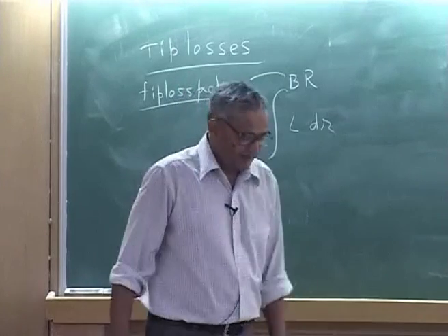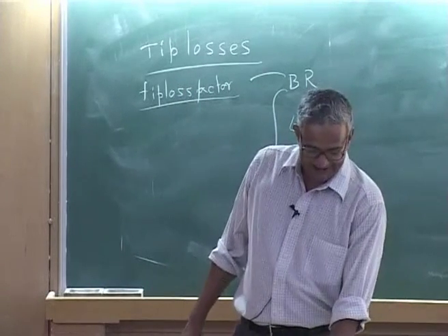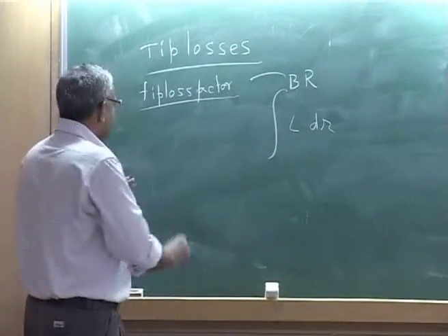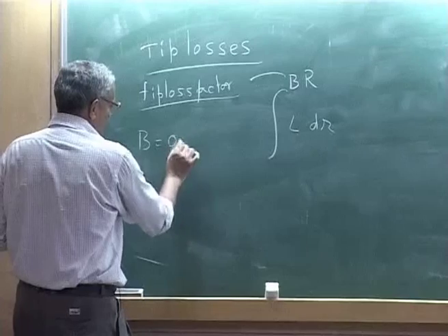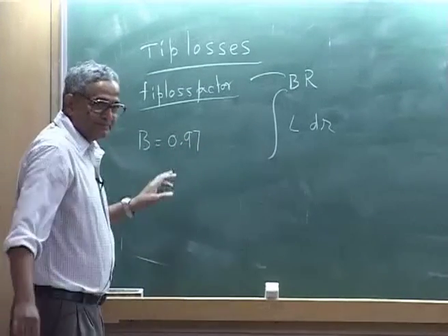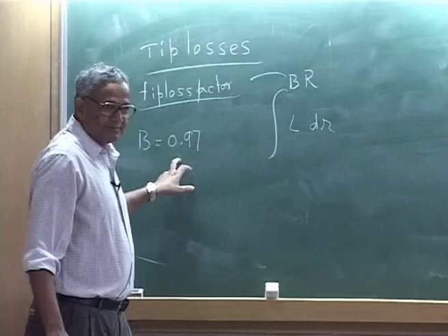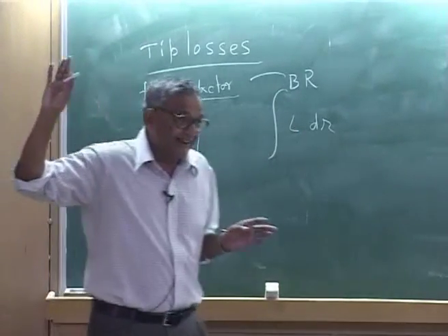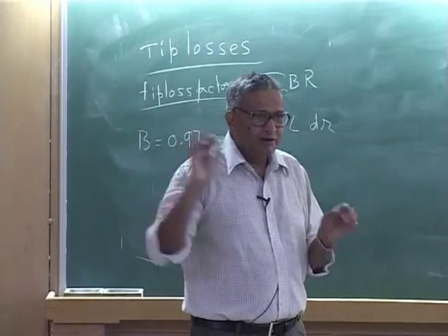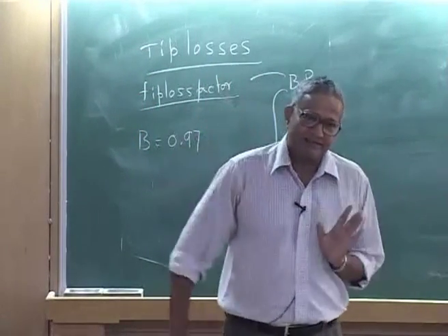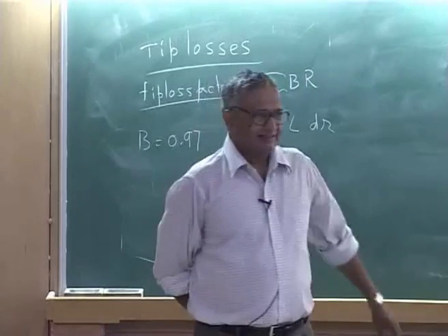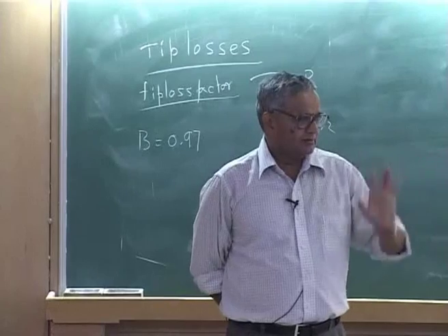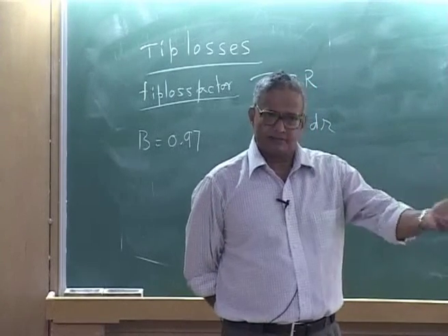They found that if you use a factor B equals 0.97, for the lift part, drag part you take it till the end, but you integrate your lift only up to 0.97 of the radius, do not integrate till the end. They find that this expression is good, because that lift whatever you theoretically predict is very good.